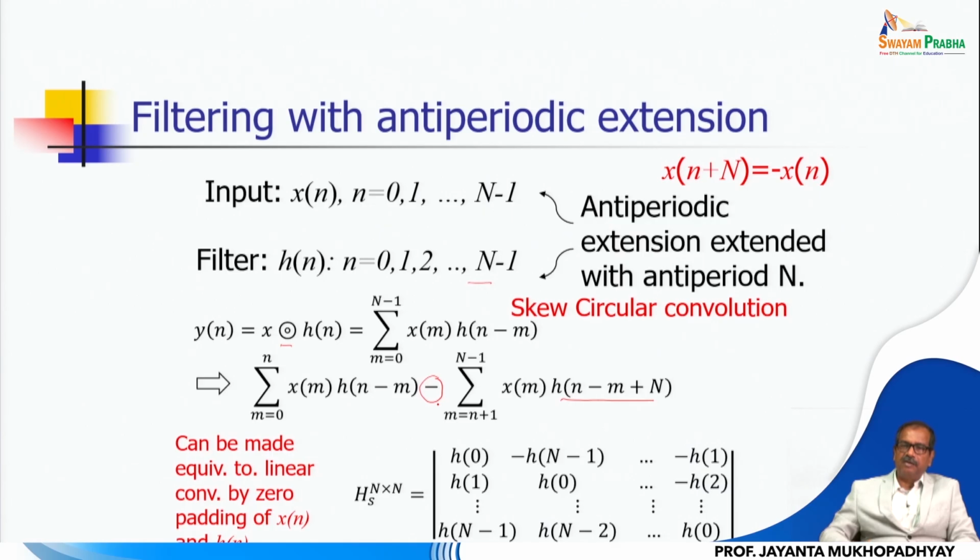So as you made the extension on the input sequence, in the input sequence also you can add zeros before and after in such a quantity, depending upon the filter length, so that the effect of the input excitation would be nullified.